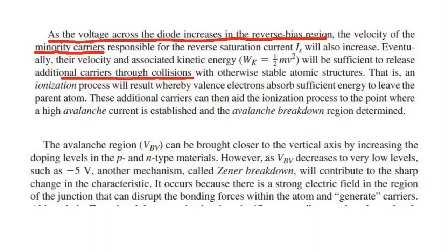So a very important factor is the VBV, this is the breakdown voltage. That means you have to reach that voltage to break down the diode, because if we stay below that voltage, it will not break down, it will remain in the reverse bias condition. But when it crosses that breakdown voltage, then after that the Zener region will happen. So this explanation is basically how it happens.